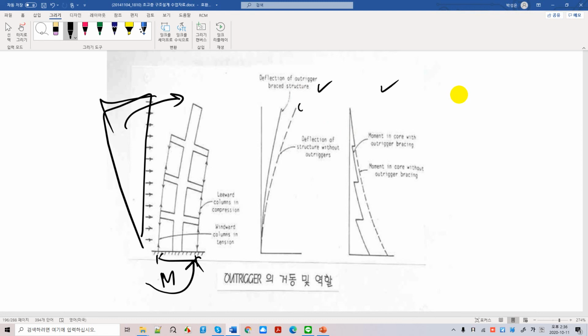And these are deflections without outrigger system. This is the deflection with outrigger system. Okay, without outrigger system, with outrigger system. As you see over there, the deflection decreases significantly because of the outrigger system, which increases the moment of inertia that we talked about a few minutes ago. And this is what the M over EI diagrams are. Right? So deflection is a function of M over EI diagrams.